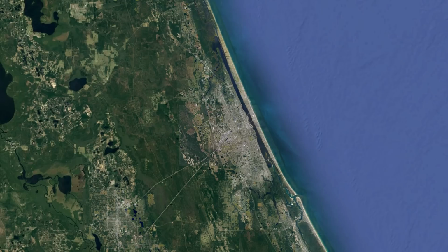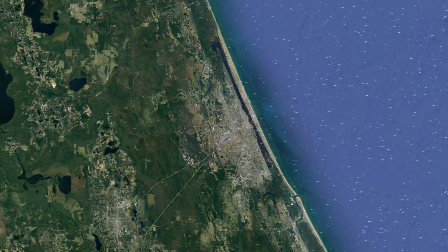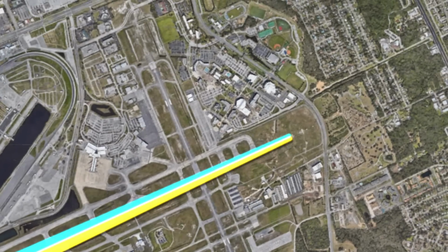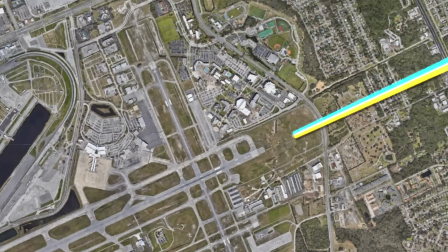This is beneficial when one runway is active more often than the other. For example, on the east coast of Florida, the wind is predominantly always blowing from the east, so most runways will be situated east to west, with the easterly runway being active most of the time. So an ILS installed for the east runway is used to create a localizer back course approach for the west runway. Keep in mind, however, that just because a back course signal exists does not mean you should use it.